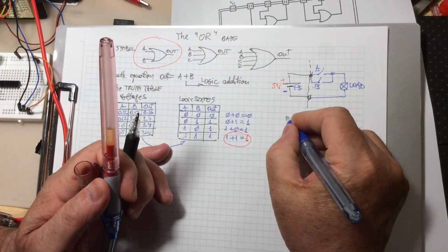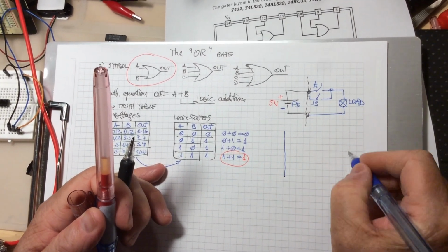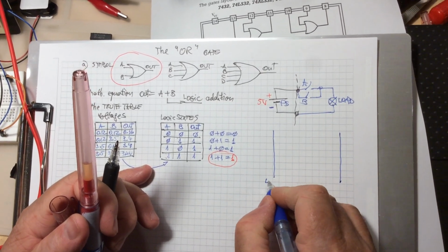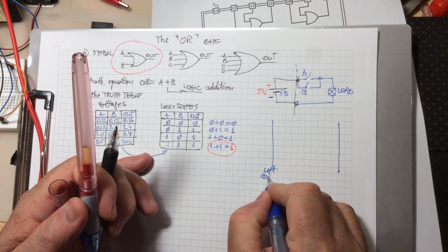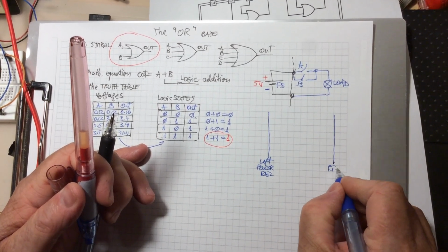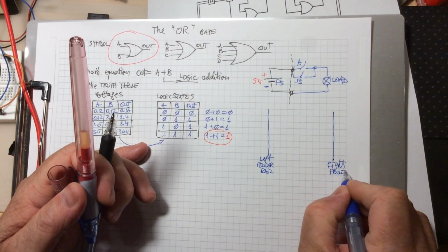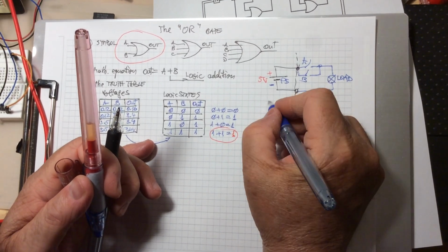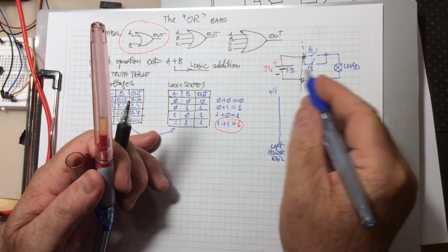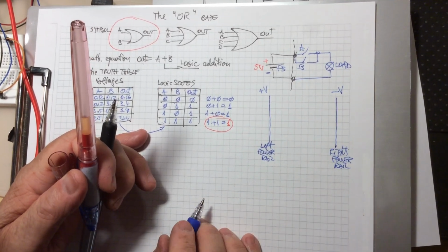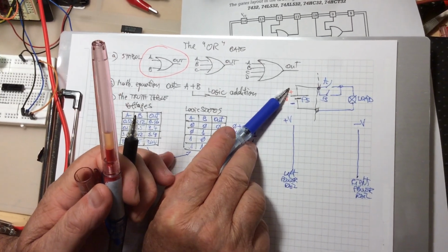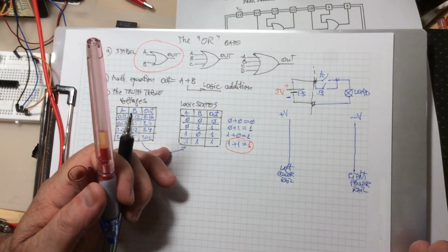However, somebody was thinking to draw the power supply like that. 2 parallel lines like this, and this is going to be the left power rail, exactly like on the railroad, and this is going to be the right power rail. This is going to be here on the left always the positive of the voltage, and here, if the power is DC, like in our example, the negative of the voltage. So the negative of the voltage is equivalent to that, and the positive of the voltage is equivalent to that. So whatever you draw between these two lines, you form an electric circuit.